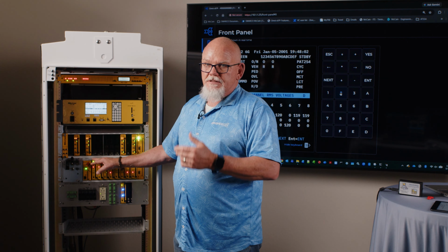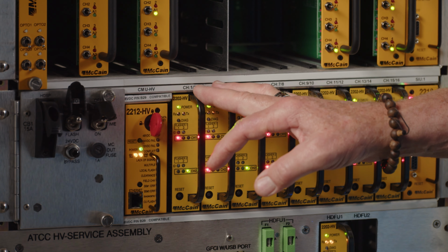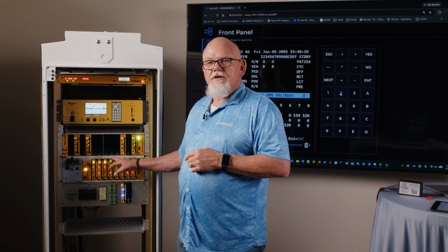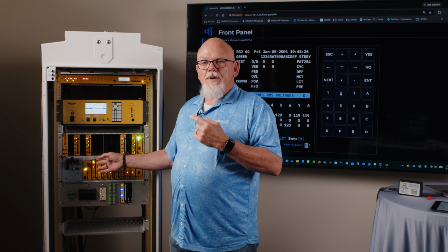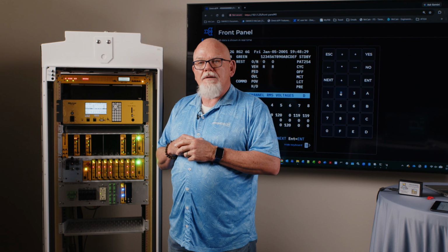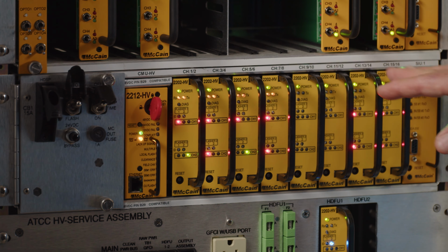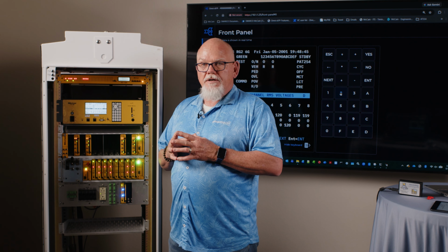The next section is our output file. Basically, this is the same as a load switch. The load switches are different in this cabinet versus Caltrans and NEMA. In Caltrans and NEMA, the load switches or switch packs were a single channel, and they ran on 10 amps, and they just had a red, yellow, and green. With these, we are actually running 2 channels. So there's 2 reds, 2 yellows, and 2 greens for channel 1 and channel 2. But the major difference is we can only run 1 amp per channel. That means this cabinet can only run on LEDs. We have this rack here, which is 16 channels. We can put up to 32 channels in an ATC cabinet. So we would actually have another output file if we were running the 32 channels.